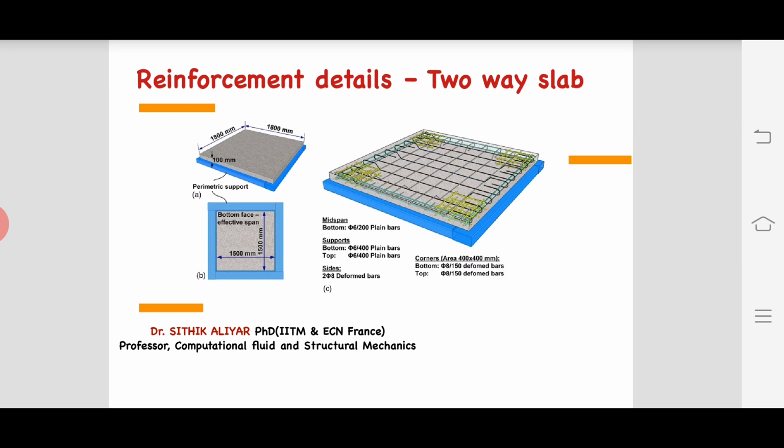Okay, so what is simply supported? You are just placing the slab over, simply supporting it over the four columns, like a bridge. Bridge most of the cases is simply supported. Or like a restrained slab. In your apartment, when you are sitting in a house or building, you can see above all the slabs are interlocked at the ends with the column and beam, correct? So in that case it is restrained on four corners. Okay, so two-way slabs are of two types: simply supported and restrained condition.